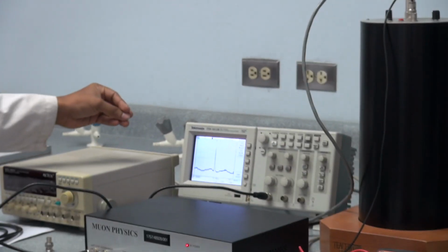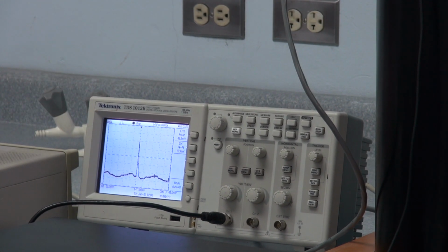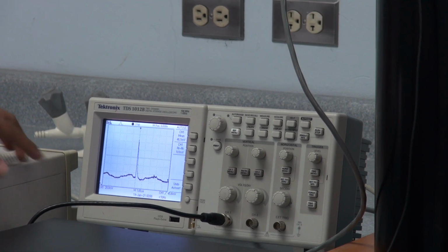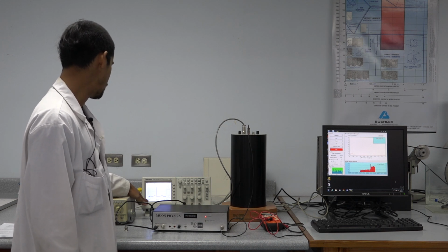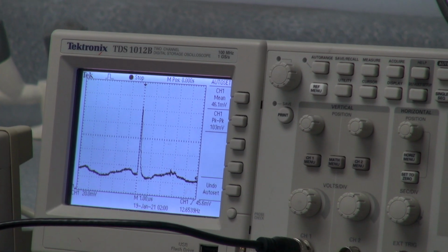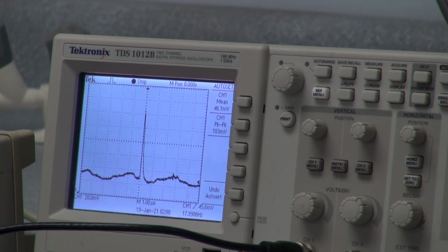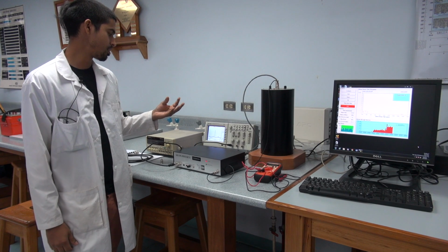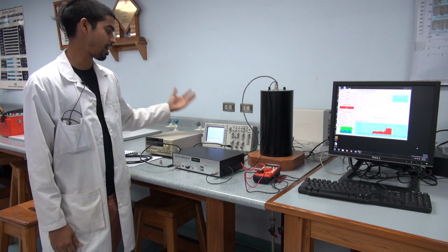So this is our signal, and we can see it resembles the signal that we got from the pulsar, except if we look carefully, we can see that the magnitude is about 20 millivolts after coming through the amplifier. So that's why we can see the noise now. You'll notice we would not have seen noise with the pulsar, because the pulsar would have given a larger voltage. So relative to the noise, it would have been large.